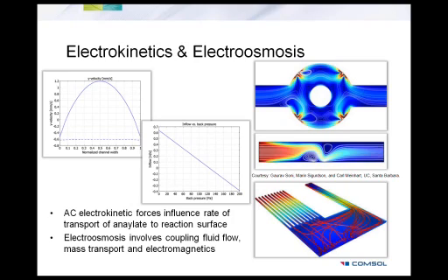So the MEMS module is actually good for doing any microfluidic simulations in addition to structural simulations and electromechanical simulations. So electrical, structural, and fluidics can be taken care of. And as I had mentioned earlier, you can also include thermal analysis in any of these models.